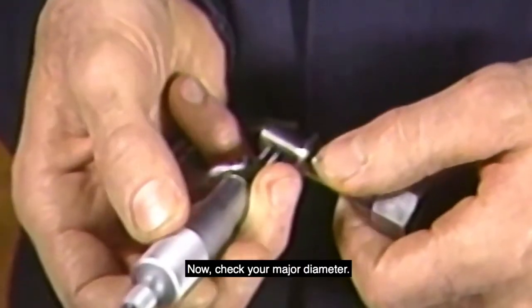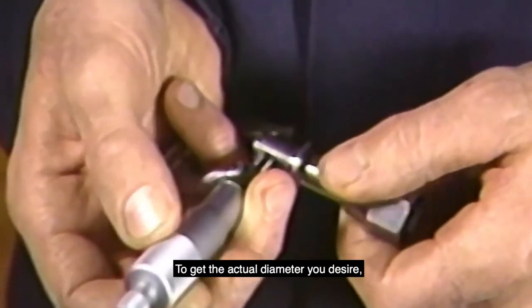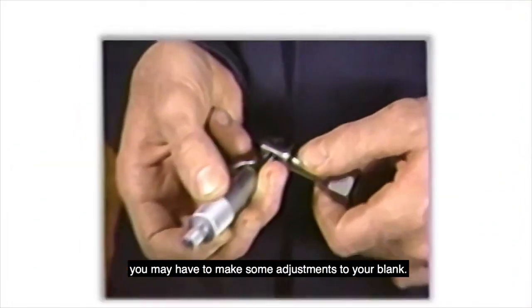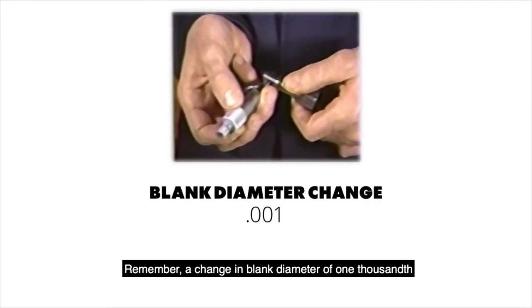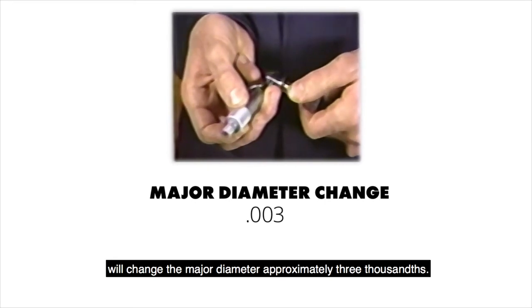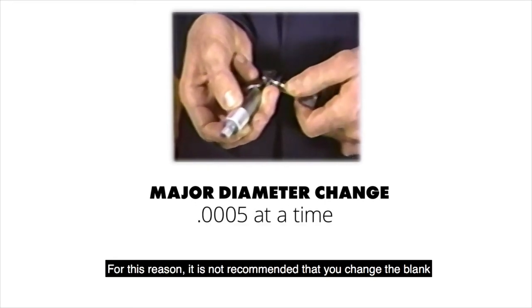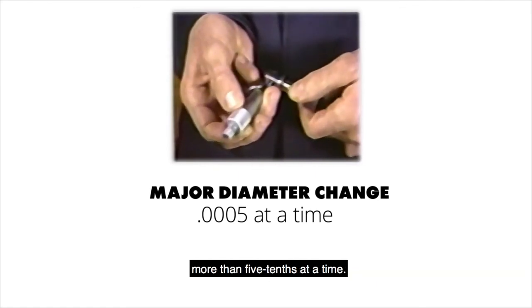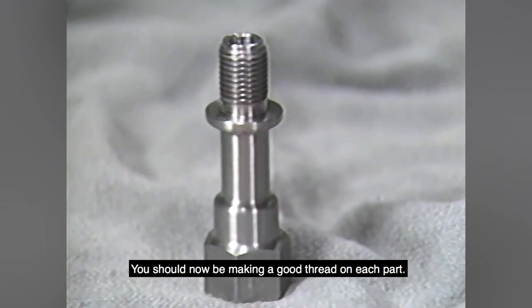Now, check your major diameter. To get the actual diameter you desire, you may have to make some adjustments to your blank. Remember, a change in blank diameter of 1/1000th will change the major diameter approximately 3/1000ths. For this reason, it is not recommended that you change the blank more than 5/10ths at a time. You should now be making a good thread on each part.